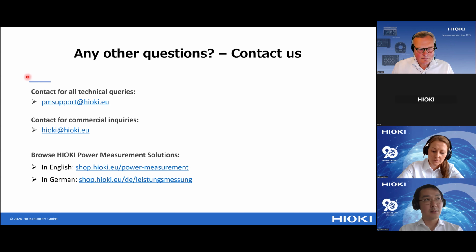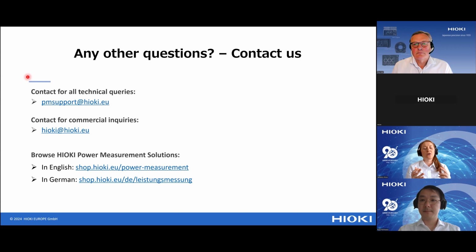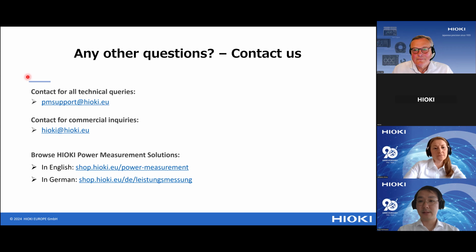In that case, it also depends on the capacity of the storage. So this means it depends practically on how many channels and how many parameters you're measuring. And we have been given here 3 different update intervals. Obviously, the slower the update interval, the more you can record. It also depends on which format you select, I suppose. Yes, exactly, binary format is compressed data.